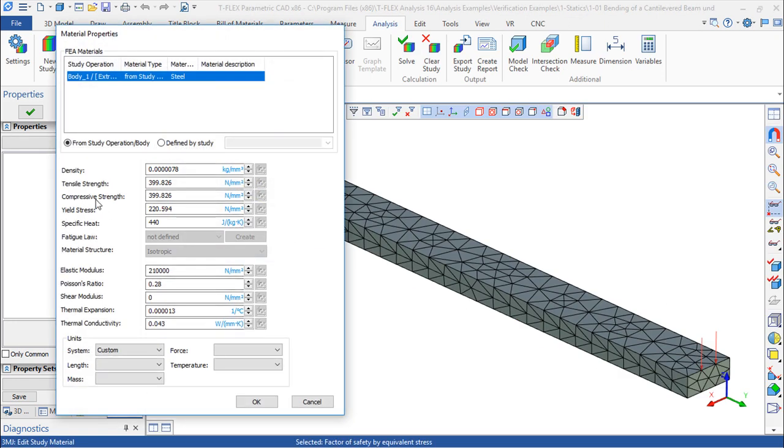So we have also this strength, tensile and compressive, and it is important to see if the value we calculated for the system is near the admissible tensile strength for the material, and in fact if it is above these values, then we have to change something on the system, because the conclusion is that we are going to have problems with that design and with that material.